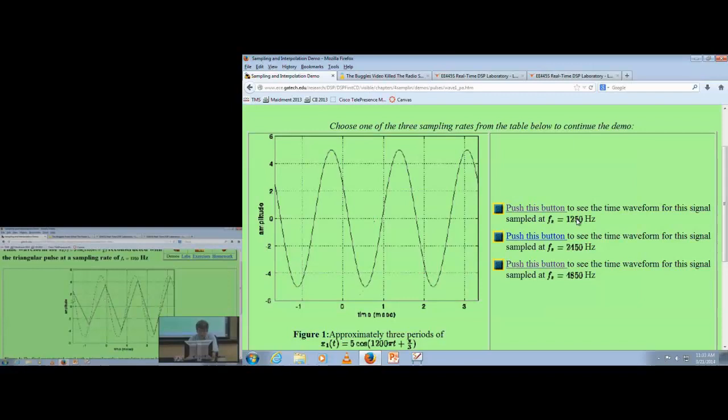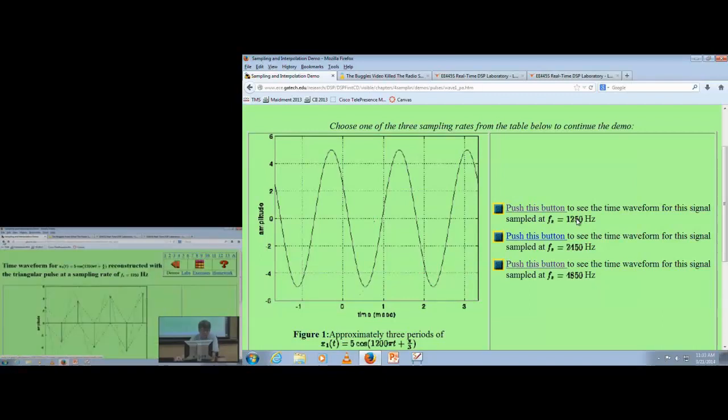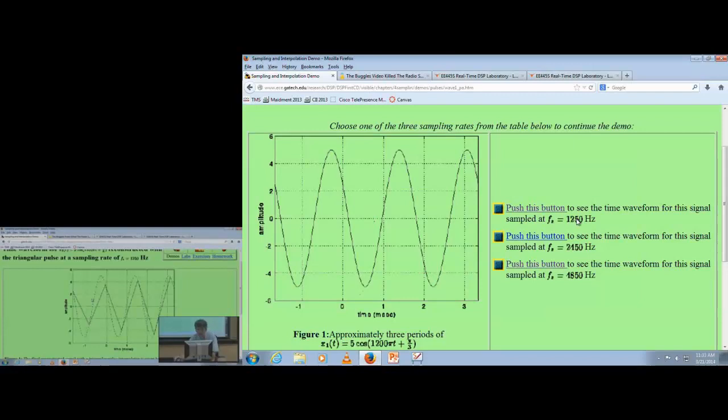But again, if we pass this through an analog low-pass filter with a stop band at half the sampling rate, it will clean up, and we'll get back a nice-looking sine wave. But not the exact one that we started with, but something that would be lower in amplitude. It would basically take this sawtooth waveform, filter it, get rid of all the harmonics, and we would get a sinusoid, but it would be offset from the original one and at a slightly different amplitude. So again, it's an example of if I don't do much work on the discrete time to continuous time conversion stuff, I have to do more work on the analog low-pass filter that follows it.